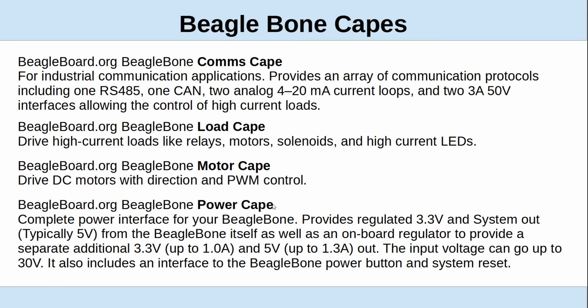One of the things I didn't mention, the Arduino's interfaces are mostly 5 volts. So it's very easy to interface it with standard TTL logic. The other ones tend to be 3.3 volts, so you need to do some level conversion in a lot of cases.